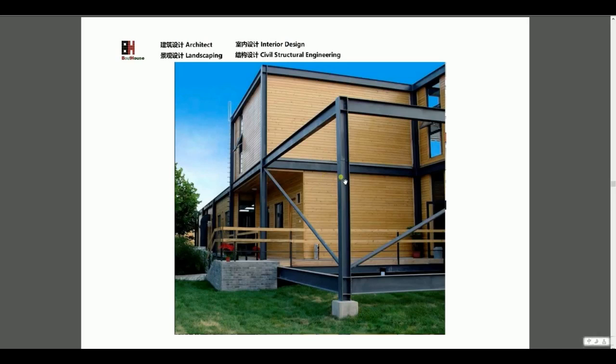This is a steel construction for the smaller building. All the main girder column is exposed to the outside. We have the corner, we have the brace. For the several bays, we just have the one corner, have the brace is enough for bracing. Bracing means making the framing stable. It's not the bearing consideration. It's just for the stability.